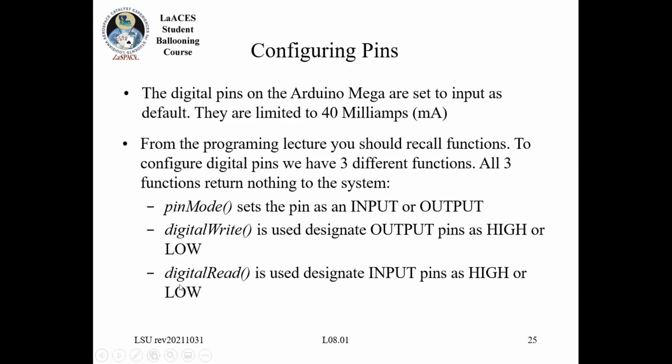But what's important is, usually if I'm calling digitalRead, I need to stick that into a variable unless I'm going to immediately use it, right? Because if I just say digitalRead pin 7, the program will get that value, but then it will just get rid of it because it doesn't know that you want to keep it. So you want to say something like pinStatus equals digitalRead(7).